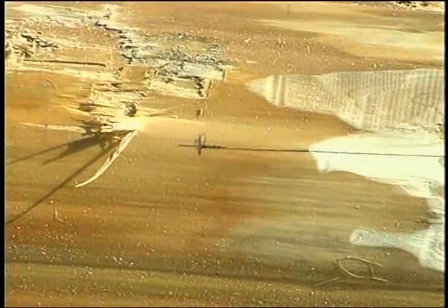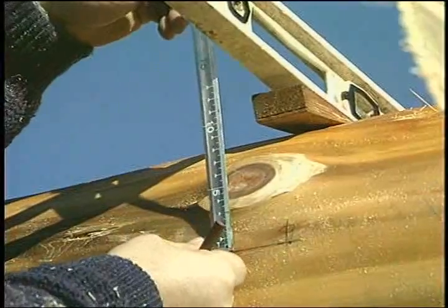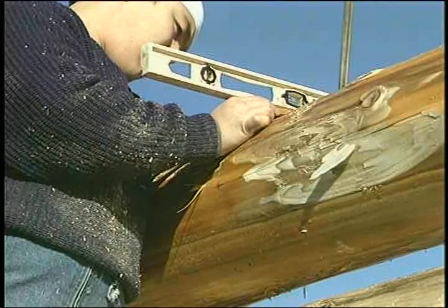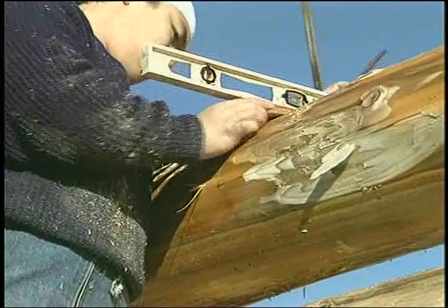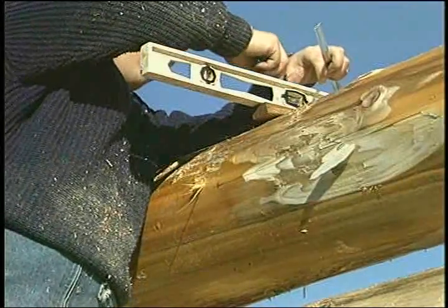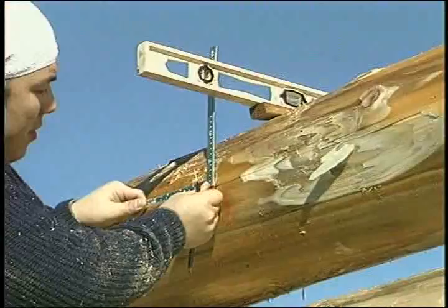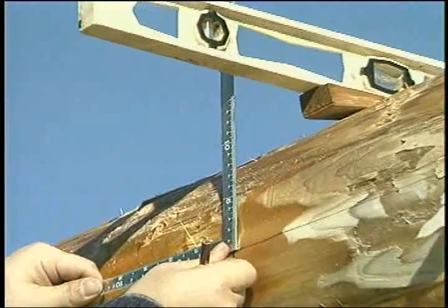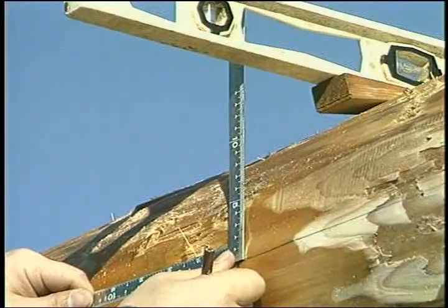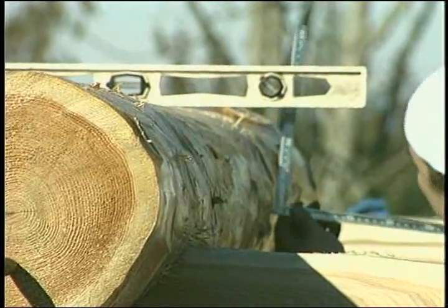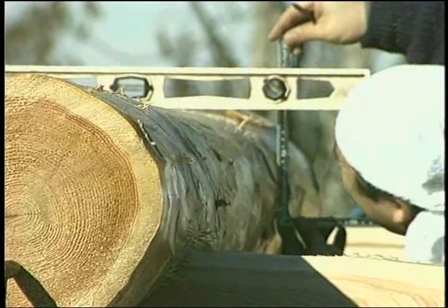On the other side of the log, you can again measure from the foundation line, or better, you can use a level across the top of the log to locate your height line on the other side. Steady the level with a wedge, then get an accurate distance to the header line. Mark the position of the level so it can be repositioned for the other side. Transfer your measurements to the other side, then snap an ink line between them. The width of the window will be located after the log has been placed on the ground.